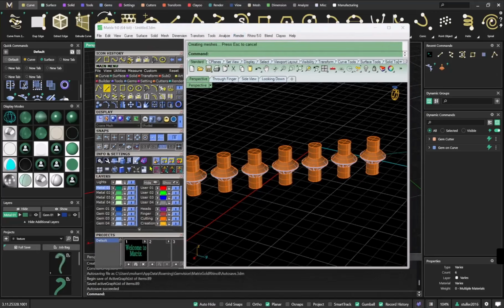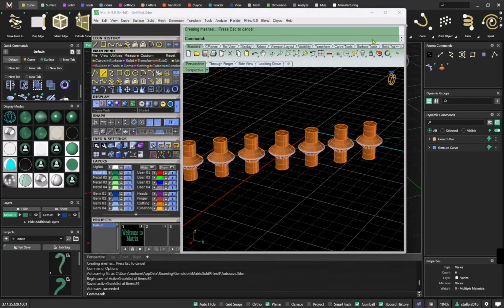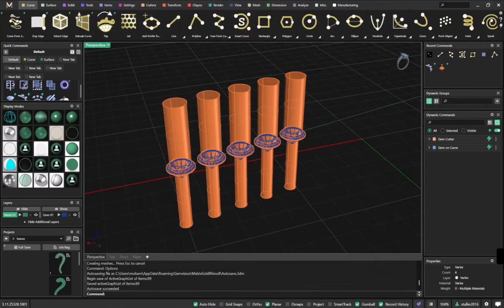Very good. And then what do we have? Snaps, right? So where are the snaps? Actually, the snap features are here. This is what we call snaps or persistent snap, turning off and turning on. So end, mid, center, quad, near, point, perpendicular, intersection, tangent. So these kinds of features. Okay, so if you go to the status bar, you will see that we already added OSnap.